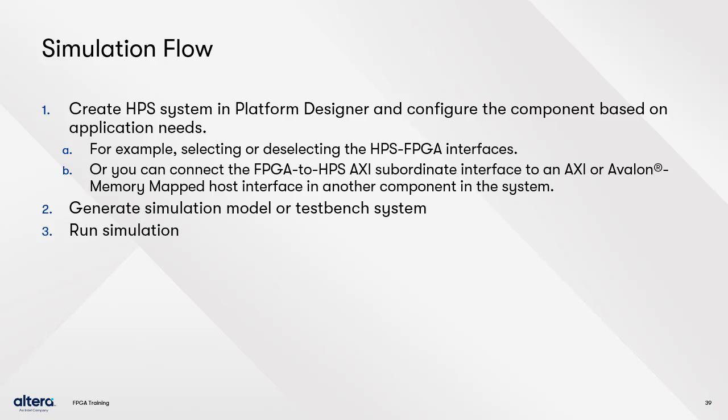Lastly, create and run simulation script for your chosen simulator. You can use these steps to test both individual components as well as an entire system. If you want to learn more about the different supported simulators, you can go to the Hard Processor System Component Reference Manual for each Altera SoC FPGA device, or visit the Resources section on this presentation. In this manual, you can also find the links to examples for designs to simulate and get started with.